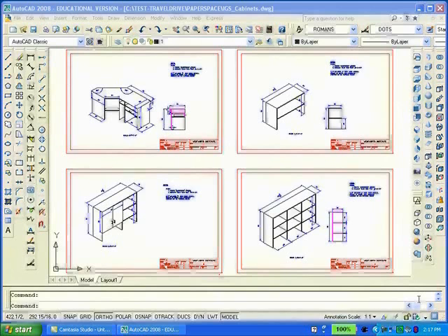When printing any drawing at a scale of other than 1:1 or full, it is necessary to always remember to set a proper overall scale or dim scale and LTS or light scale. It doesn't matter whether plotting in model space or paper space, it is vital to properly set those two variables. If the variables of dim scale and light scale are not set correctly, you can have dimension text that prints too large or too small. You can also have hidden lines print as continuous lines.